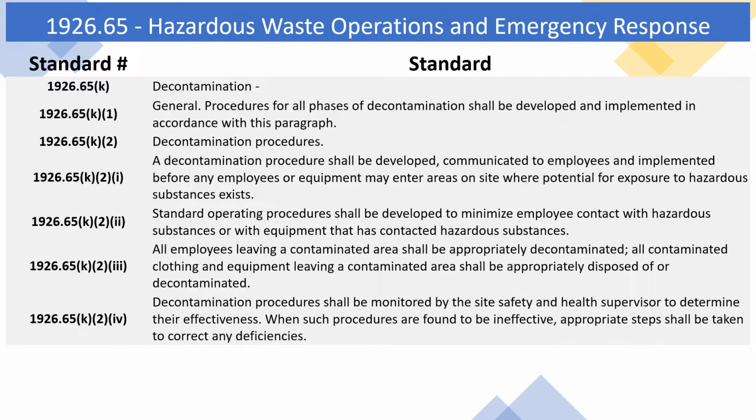1926.65 K2-2 Standard operating procedures shall be developed to minimize employee contact with hazardous substances or with equipment that has contacted hazardous substances. 1926.65 K2-3 All employees leaving a contaminated area shall be appropriately decontaminated. All contaminated clothing and equipment leaving a contaminated area shall be appropriately disposed of or decontaminated. 1926.65 K2-4 Decontamination procedures shall be monitored by the site safety and health supervisor to determine their effectiveness. When such procedures are found to be ineffective, appropriate steps shall be taken to correct any deficiencies.